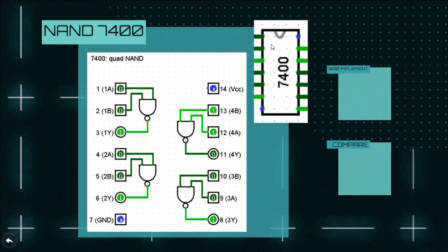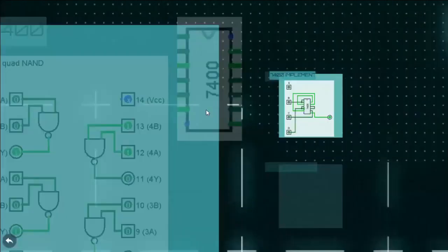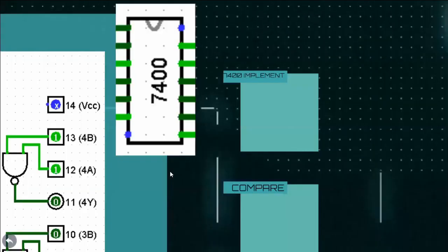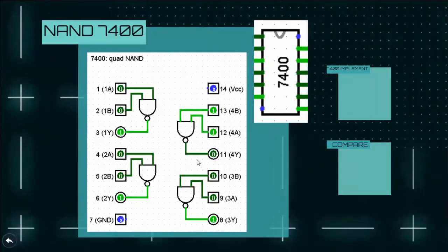So the best performing circuits or digital systems utilize NAND gates, and the optimal implementation would never waste any of those gates inside those chips. So right here, we just would implement the reduced version we just did with this 7400 integrated circuit. As you can see here, you have 4 NAND gates that can be used.